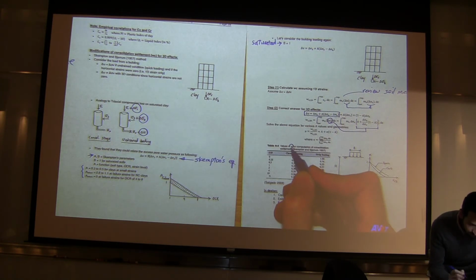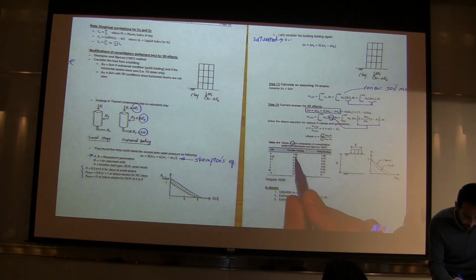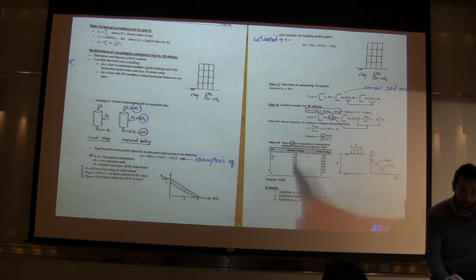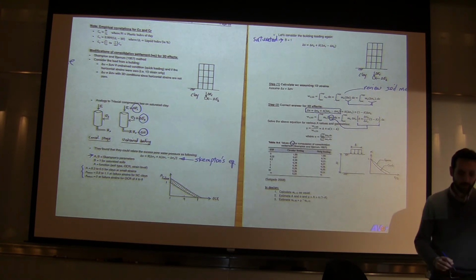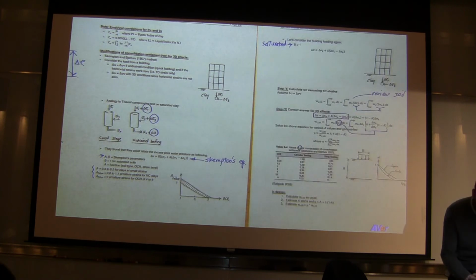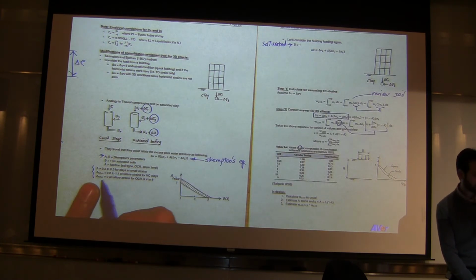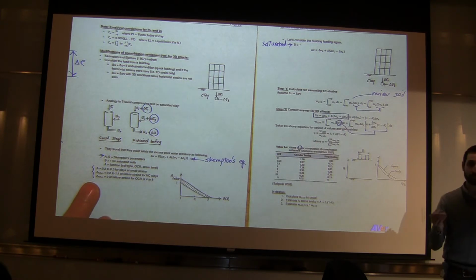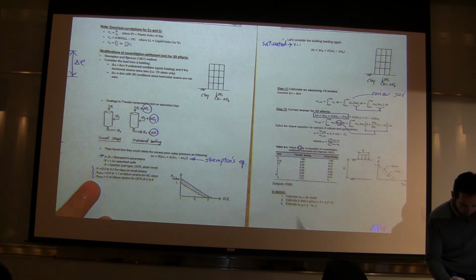This table gives you alpha. It goes from 1 to 0.25 or 1 to 0, depending on what type of footing you have. So you look at this, you get your alpha, and A is given on page 28, at the bottom of page 28. There were different ranges of A given, and if I ask you to do this calculation, I'll tell you what A to use.